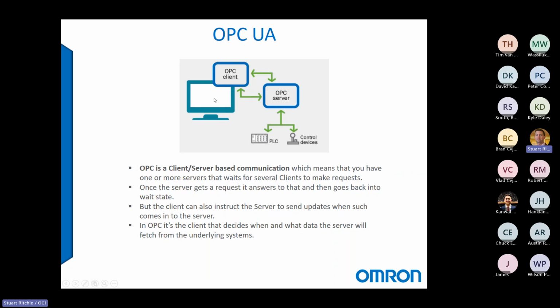Now we'll quickly talk about OPC-UA. So this is a protocol that's been around for quite a long time now. It's commonly used in SCADA communications. Most of the major SCADA players have an OPC client built into them. Now, our PLC is a server, so it's not a client. We couldn't talk to another OPC device if we wanted to. We're a server, we sit there and wait for requests, and we serve those requests. Being that we're a server, it's actually very easy to set up OPC.